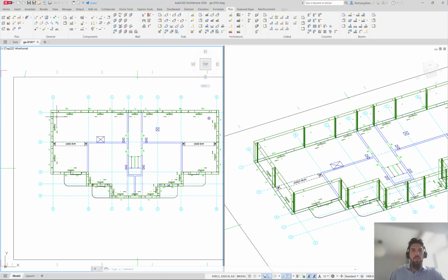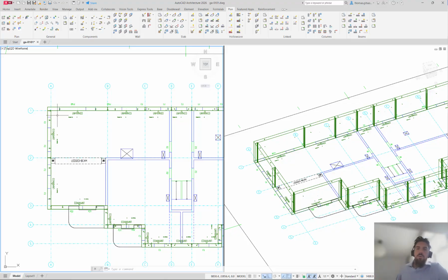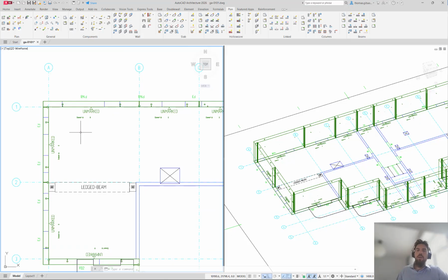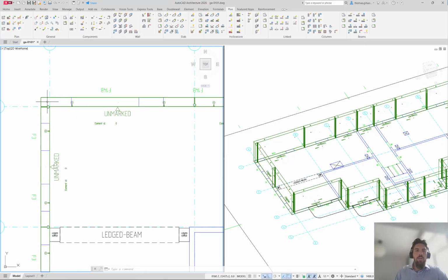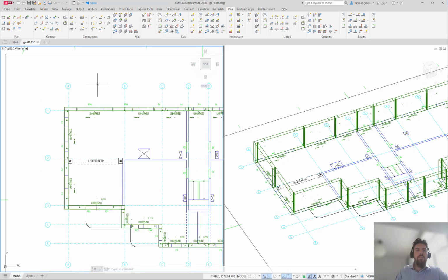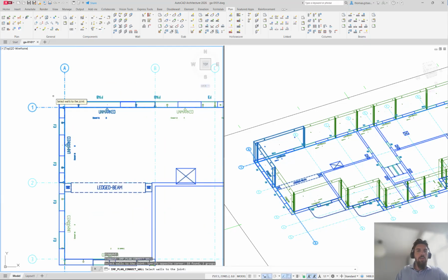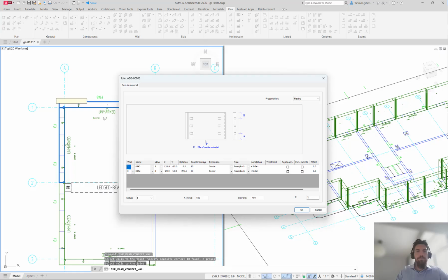precast type of elements. Now you have to start working around where or how I can connect my walls. Of course, again, I'm a little bit smart, so I have predefined and pre-created some joints here that are going to connect my edges, and I'm going to select this function called connect walls, add my joint. This is my pre-specified joint.